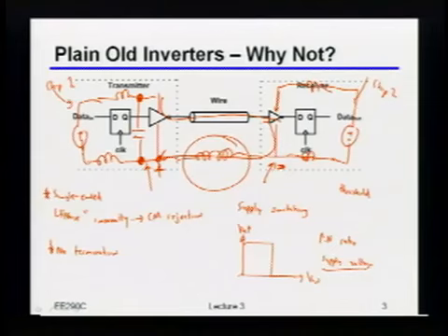So there was something else that I think maybe Linkai or somebody brought up, which is, right now my swing is just set directly by the power supply. Right? So if I've got a 1 or 1.2 volt supply, and I want to run some swing onto this 50 ohm line here, then at least temporarily I'm going to be burning something like 20 milliamps. Okay? So if you were really to do high-speed signaling with something that looked exactly like this, it's probably going to end up burning quite a bit of power. Okay? And we'll talk some more about why exactly that is a little bit later.